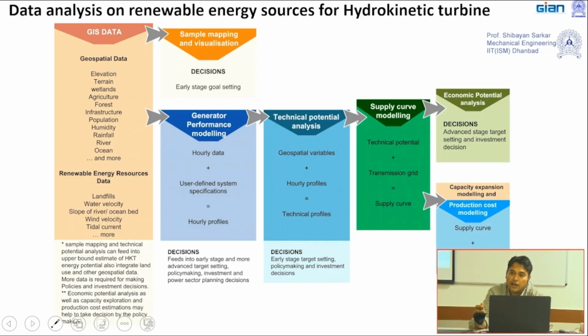If some sites provide measured river discharge data, that is okay. If that is not available, you can estimate the river discharge through the terrain as well as the precipitation. How much precipitation generally occurs in a particular catchment allows you to calculate how much discharge can be available in a particular stream.